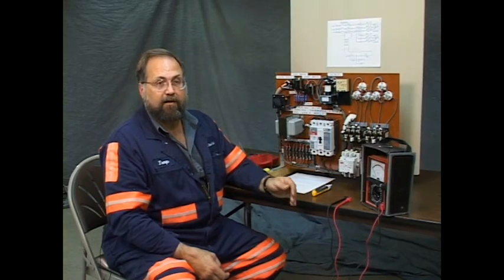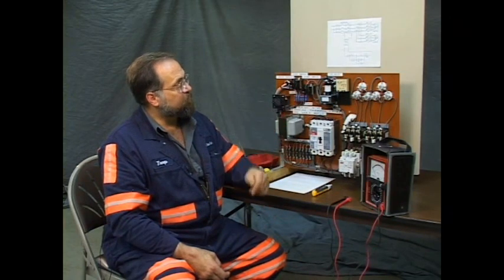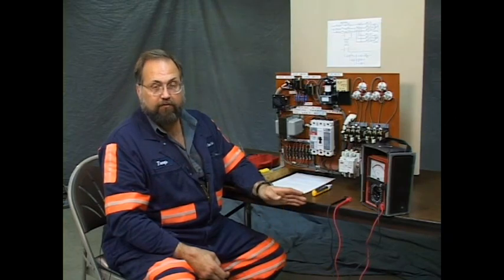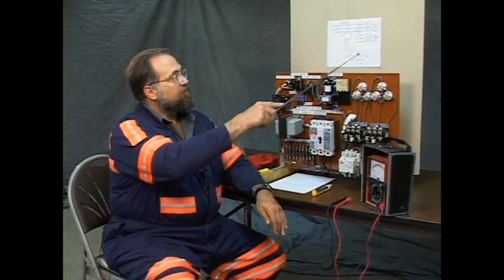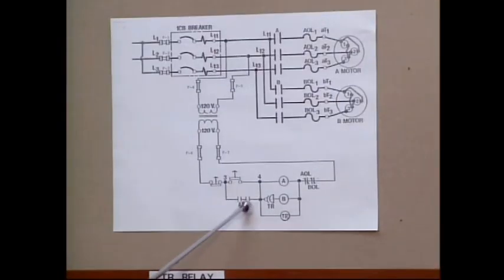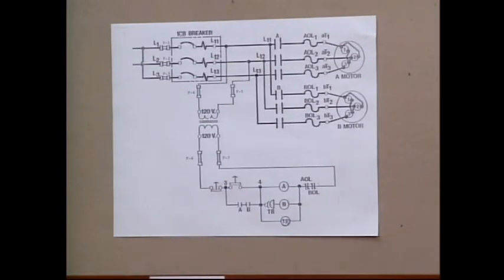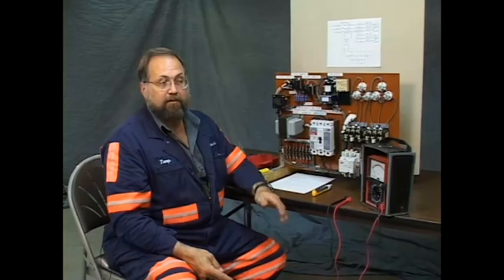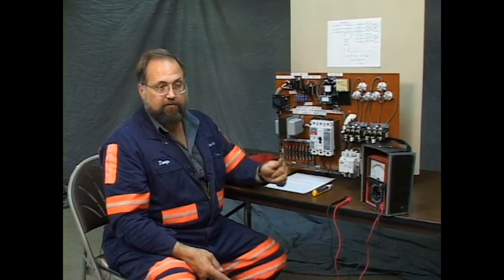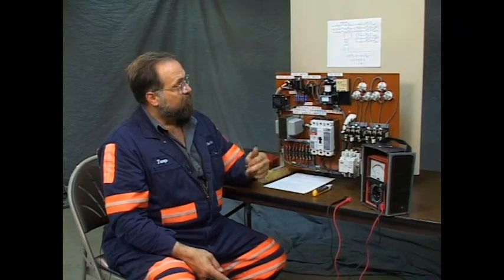You need to have a definite control where someone presses a button, operates the circuit, started. That's the point in using the momentary. And with the interlocks, give you a holding circuit to allow you to turn it loose. Now, when it stops, these normally open contacts here, they revert to their normally open status. And when you release the start switch, it reverts to its normally open status. So nothing's happening until you press the switch. You initiate by closing the switch to start the motors.